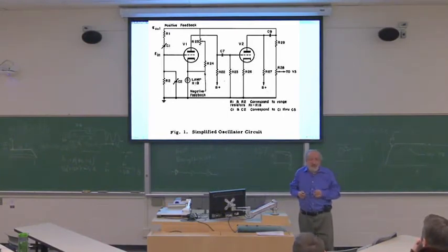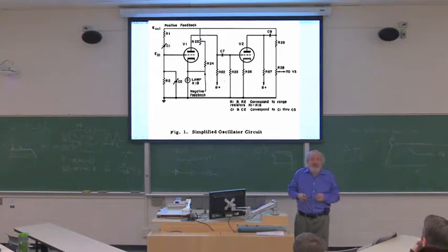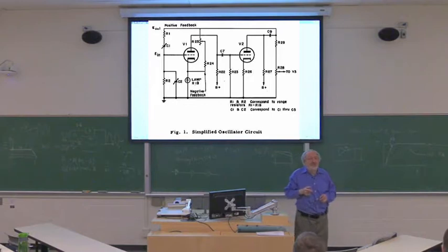And the way this works, an incandescent lamp changes resistance a lot as it glows brighter and brighter. Because it glows brighter, the filament gets hotter, and if the metal gets hot, the resistance goes up. You know that, right? For example, if you take a regular incandescent light bulb, and it says on it 120 volt, 120 watt, okay? And you measure it with an ohm meter.